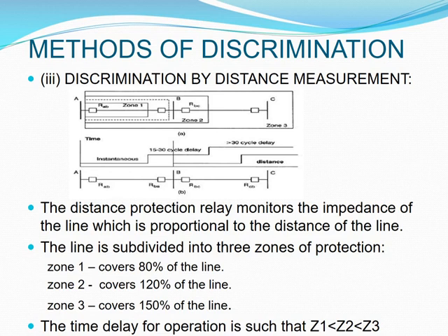So looking at the diagram that I have over here, can you see that I've got 3 substations or 3 bus bars? I've got one at A, I've got one at B, and I've got one at C. So my zone 1, you can see that it goes from A up until just before you get to B. So that would represent the 80% of my line.